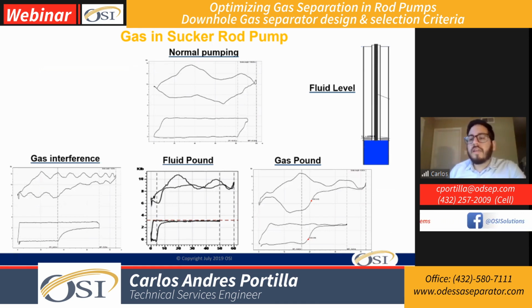We can see if we are producing below the bubble point, and if the pump is ingesting a lot of free gas and we still have an important fluid level, then we can say that we are seeing the gas pound issue right here. We can approach that problem by increasing the pressure of the casing when we have enough fluid level, so we can keep that gas back in solution.